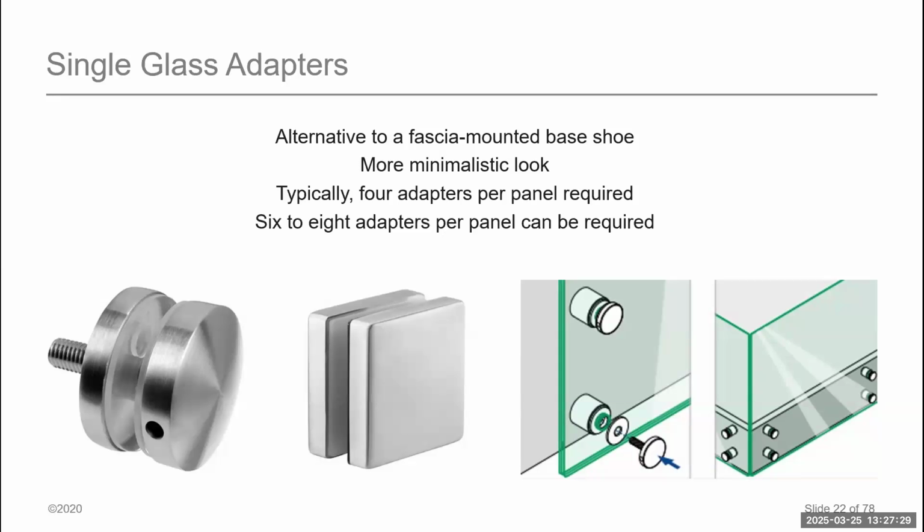The other thing we also see is we do need to handle the overall stresses that are being placed on the glass. Similar to a base clamp, this is a point loaded cantilevered glass system. And again, you will most likely be required to do an FEA.